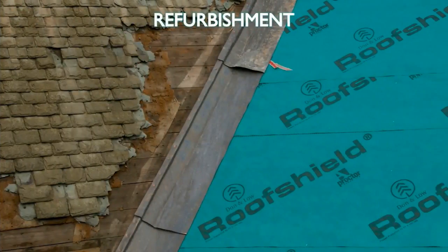In refurbishment projects, there may be pre-existing condensation issues to resolve, particularly related to convection tightness and cold bridging. Older structures were not usually designed or built with much thought given to these issues, so it might not be that straightforward to resolve these problems, either in practice or economically. The building may also have been modified or upgraded over its lifespan, and additions such as double glazing, blocking up chimneys and ceiling drafts may have created condensation issues which did not exist before.